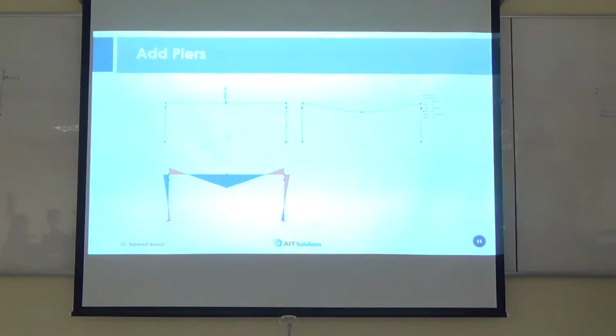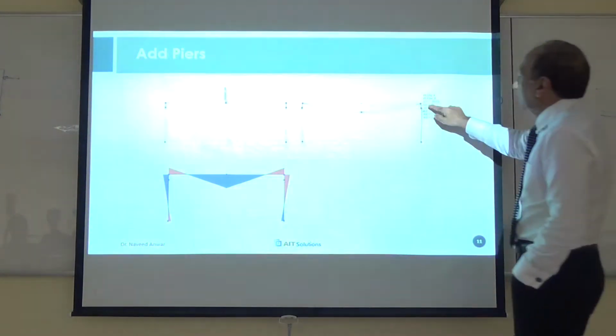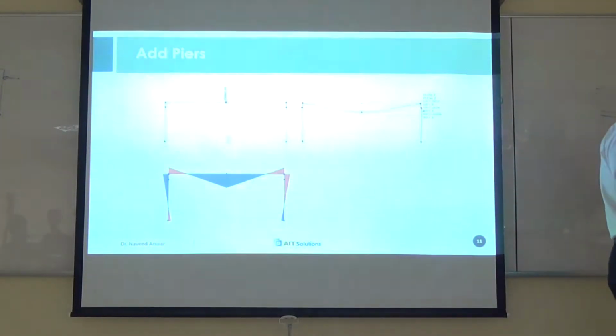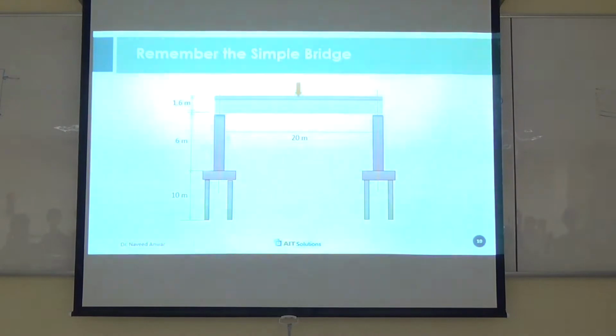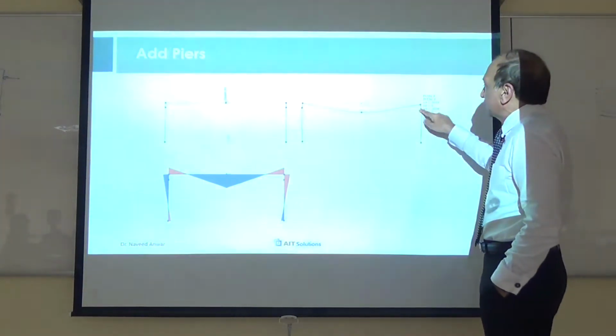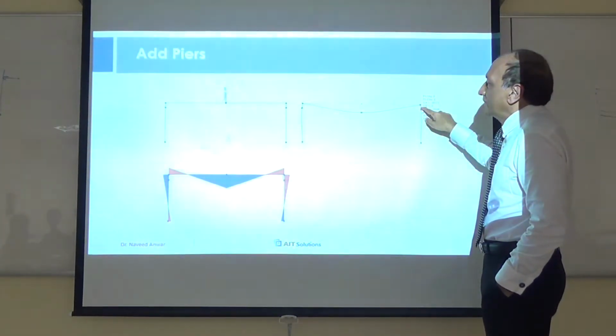So let's combine the beam and the piers together, and we link them by something, because they are not fully connected, they are not framed. They're not directly connected, so you cannot have a rigid frame. It's not a building frame, it's a bridge, which means there has to be some kind of connection here to represent the bearing.